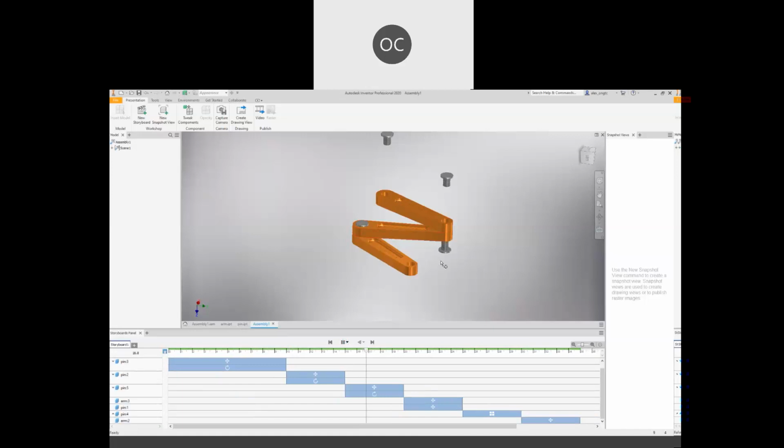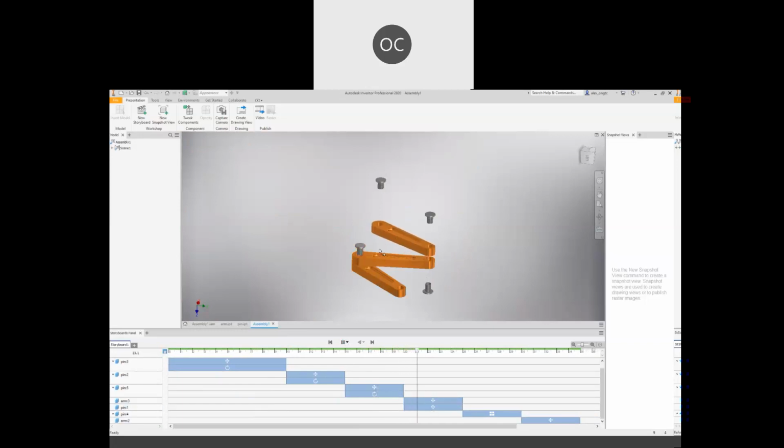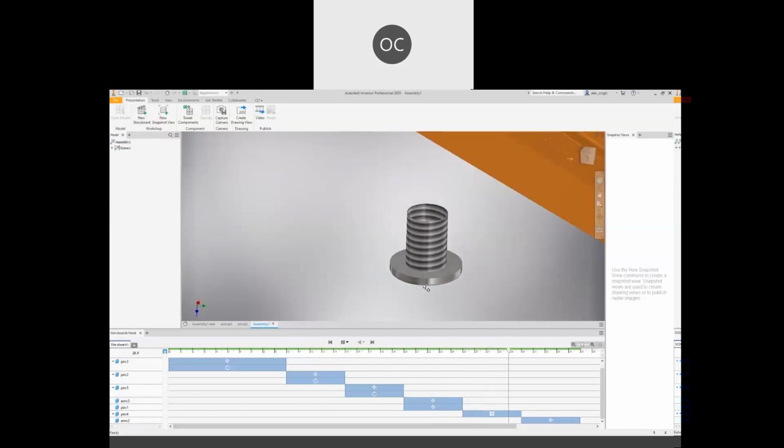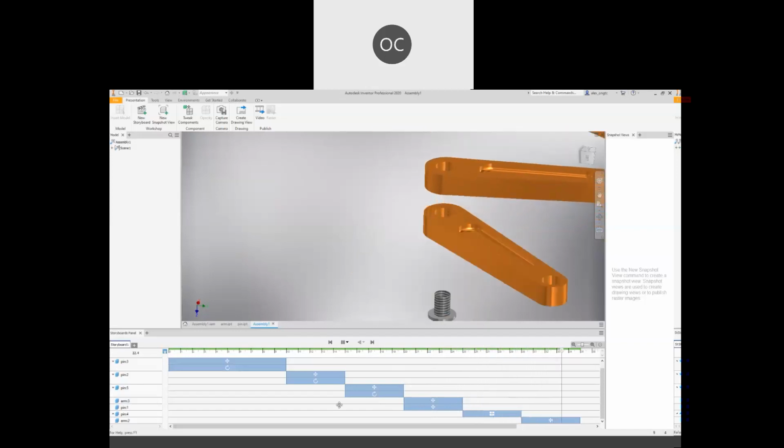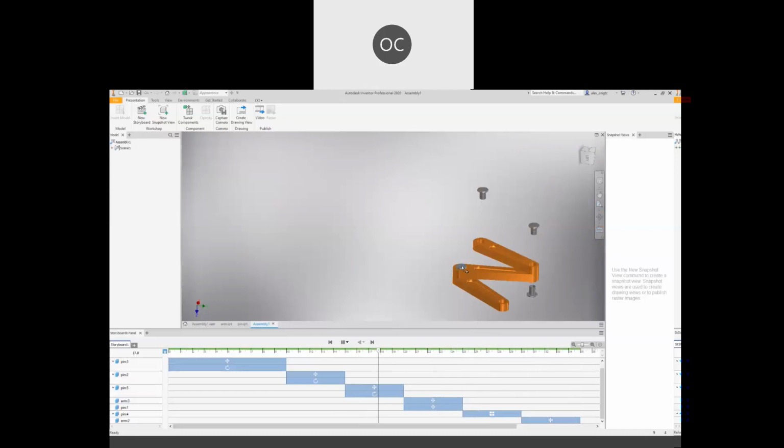Okay, so you see it's actually rotating, right? So here also, you don't have this one, you can rotate. This one you have rotating mode later. So how we can actually add that will be, okay, for example, this part, I think this part I don't have the rotation there. So I can go to tweak component, still in tweak component. So if you click on your component here, you are in pin 1 here, 3.1 here, it's movement up. Here is move. So another one here, which is available, will be rotate. Okay, you see rotate over here.